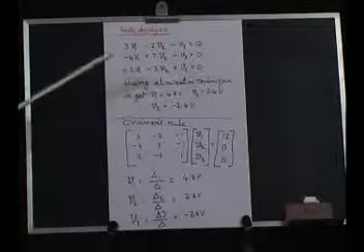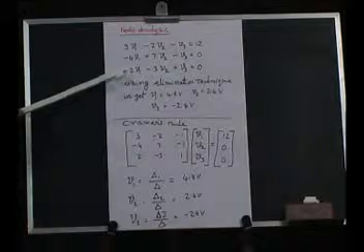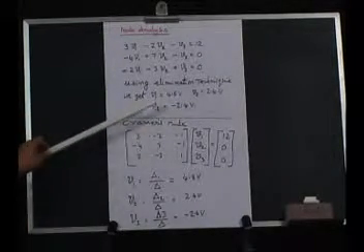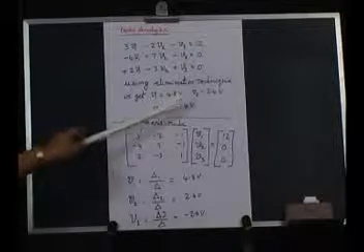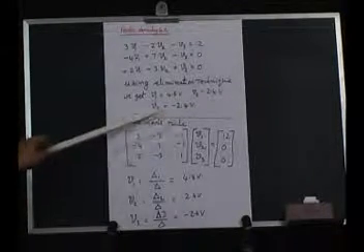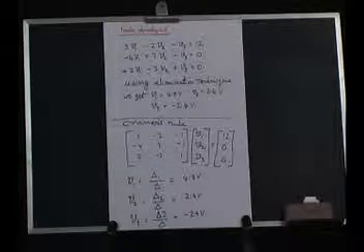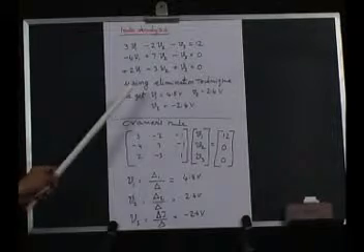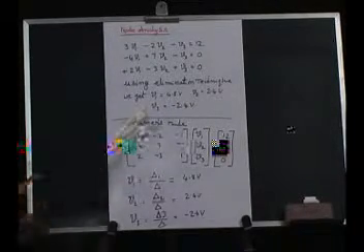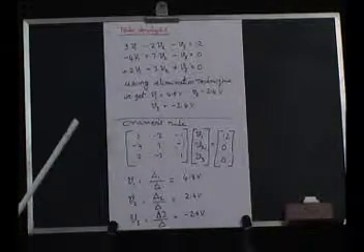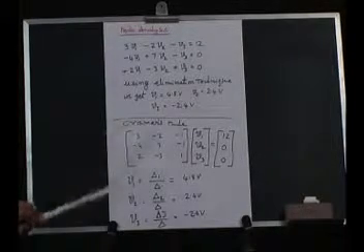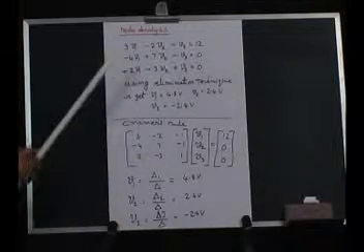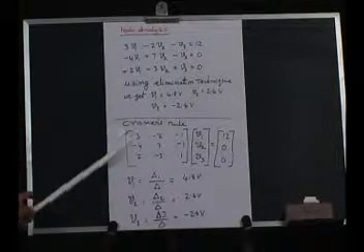Then we can simultaneously find the solution of those 2 equations, and you will find that the solution by the elimination technique is V1 equal to 4.8 volts, V2 equal to 2.4 volts and V3 equal to minus 2.4 volts. That means we have analyzed the network and found the values of V1, V2, V3. With that we can find the branch currents, the power, and the energy.